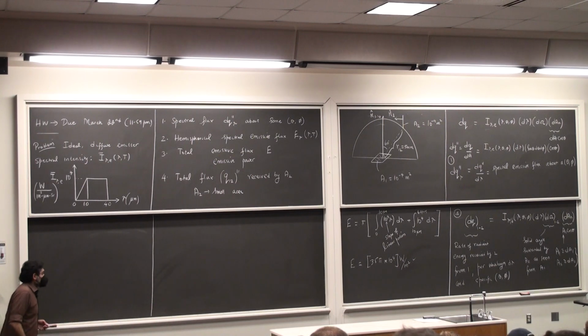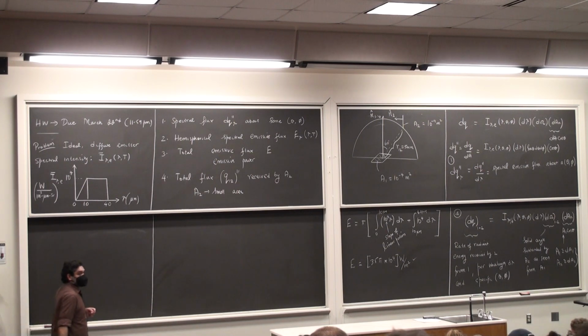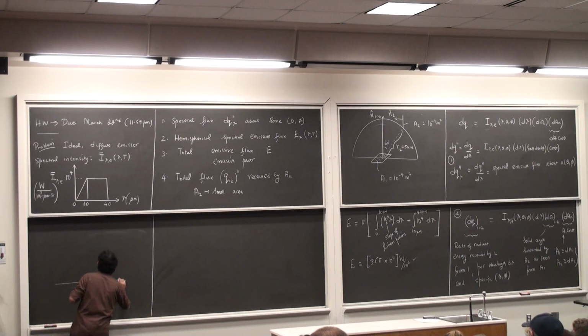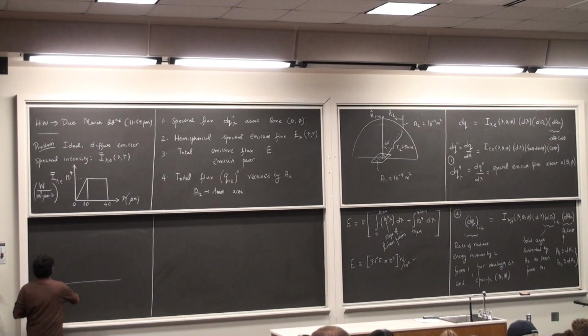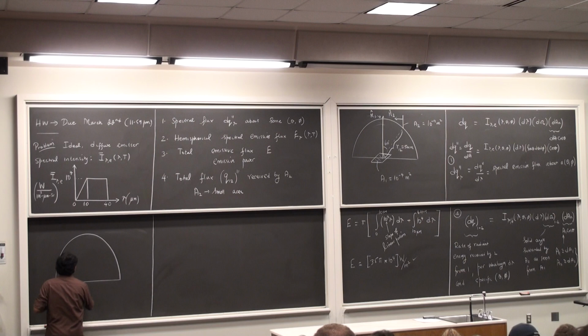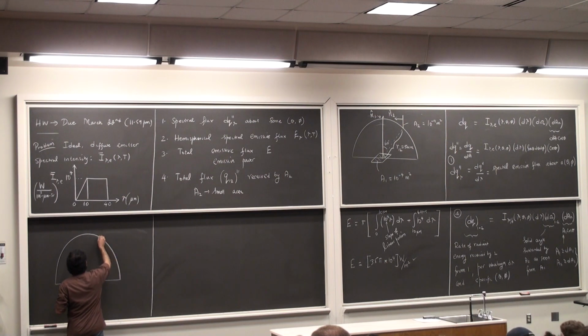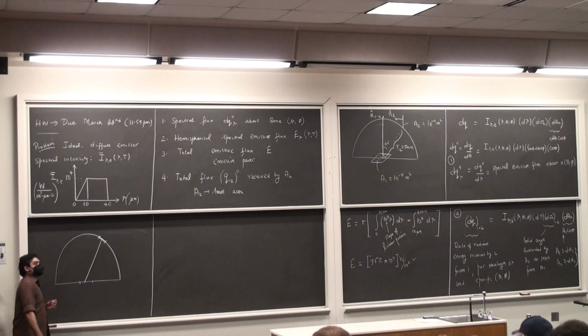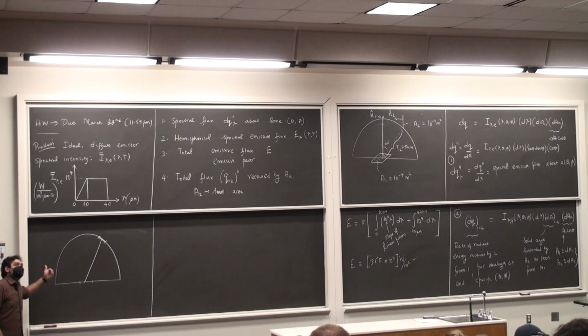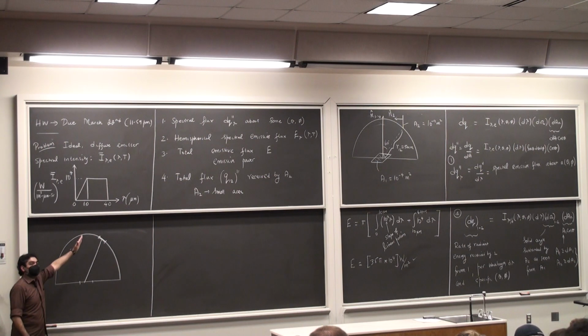Let's start cracking them up one by one. So d omega 1, 2 is the only sticky creature here, and this is how we take care of it. By definition, for the solid angle subtended by a surface which is sitting on the hemisphere above a surface that is emitting radiant energy, it is imperative that the area normal of the receiving surface, by the definition of the solid angle, is aligned with the line of sight from the sending surface or the transmitting surface.